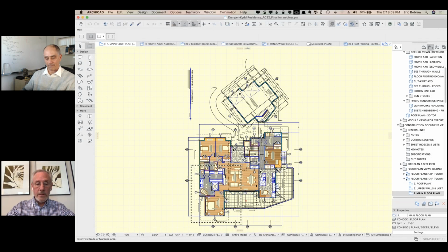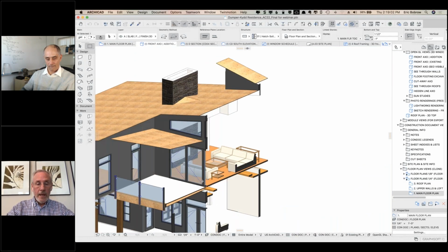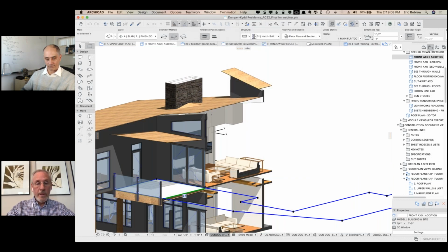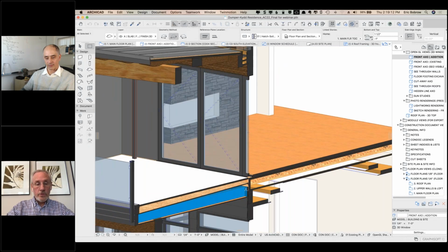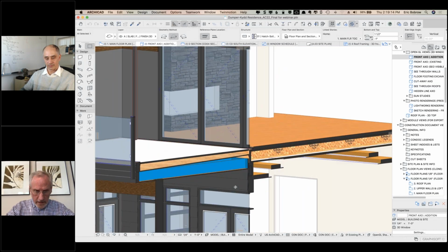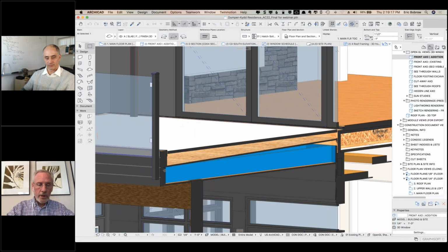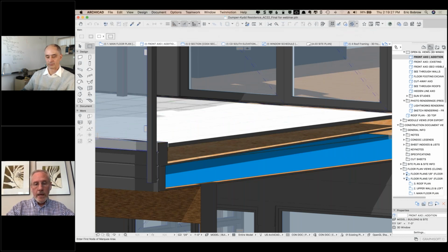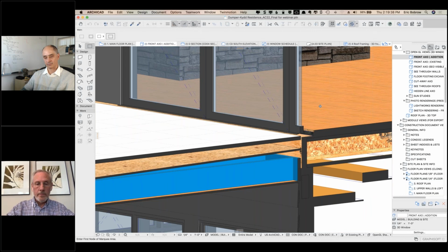and it has a slope built into it that slopes towards the outside underneath, and then a torch-on roof membrane is applied to that, and there's a curb on the front side. You can probably see it there, and then I haven't put all the little support pucks, but basically then there's adjustable pucks that sit on that roof deck and support these pavers, and then you can level them all out so that they're perfectly level, even though your patio deck is sloping to the outside. And then there's drains that are basically at the inside of the parapet, so you don't see those. Well, you do see them eventually, they come down.